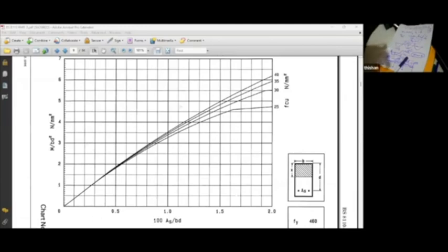Even if you go up to 4, if your grade of concrete is high, you can still simply reinforce it, but a lot of reinforcement is needed. So that's why I like a maximum M over bd squared of about 3. Here, little reinforcement. When you go up, more reinforcement. So I like a value like 2.5 to 3. Even 2.5 is okay, very little reinforcement. Can you understand that, Bandhuka?